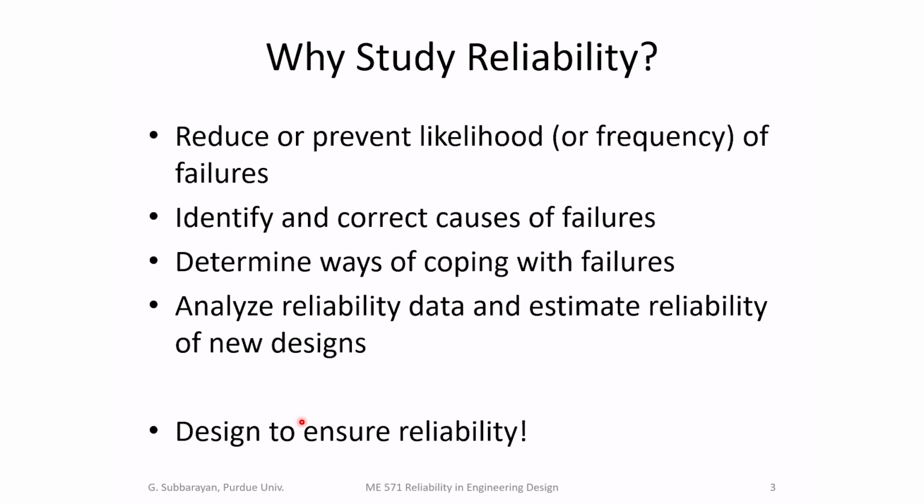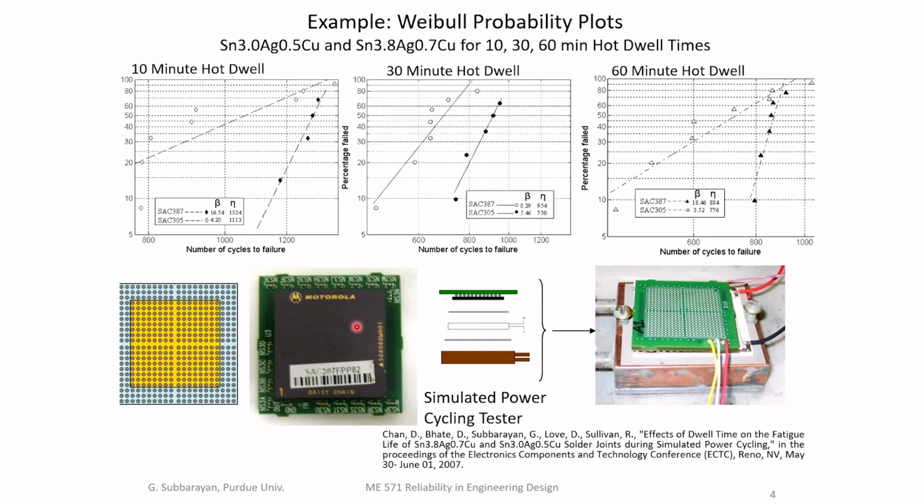Here is an example of what I mean in terms of analyzing reliability data. This is again from my research. I'll discuss this in the case study in more detail. So here was an electronic component assembled onto a circuit board, and it was tested by a special technique that we had developed in my lab called simulated power cycling, using a Peltier heater to heat this component from an external source.